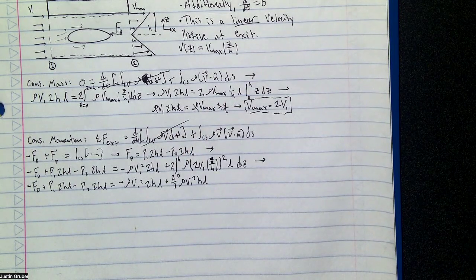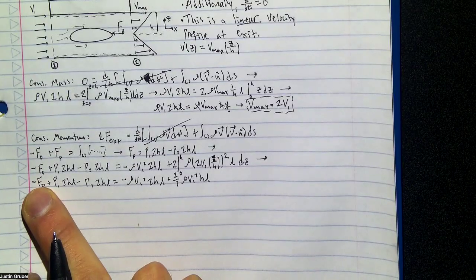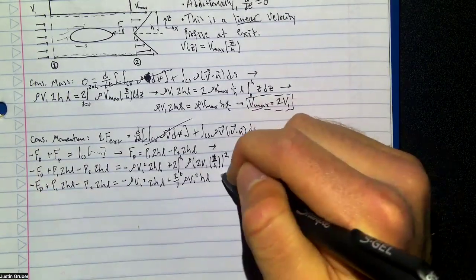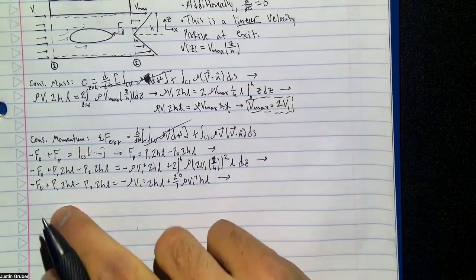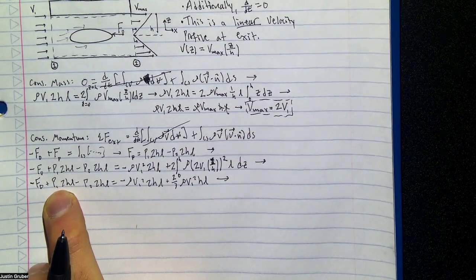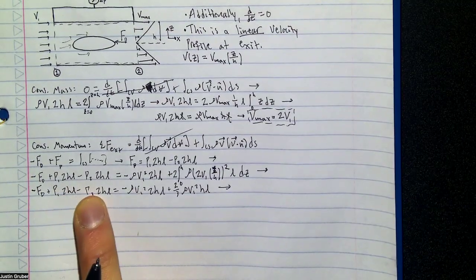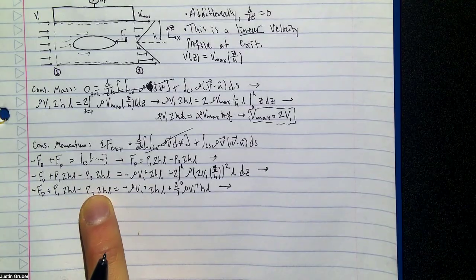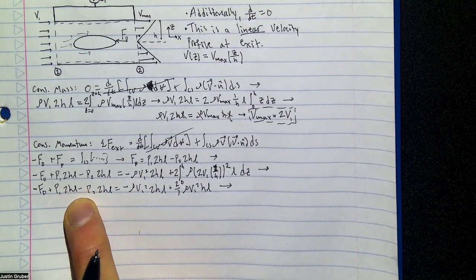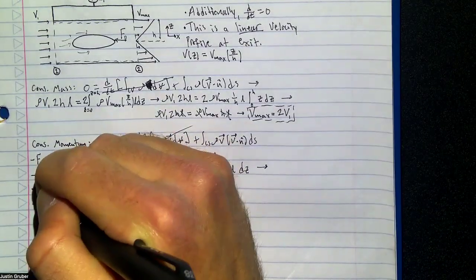So anyway, now we're just going to keep going. We end up wanting to solve for this FD. If you're on the ball, you can see since we want everything in terms of a pressure differential anyway, a delta P, P1 and P2 have the same 2HL. So we can call this P1 minus P2. That is our delta P. So let's keep going.